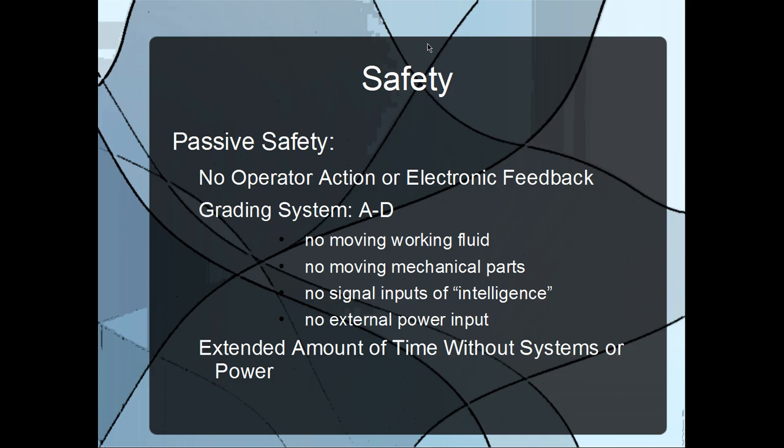By doing this, many old-style active safety systems are either no longer required, such as loop-installed and pump-driven emergency cooling systems, or are only installed to meet legal requirements, such as borated solution injection systems. Now, combined, the passive systems of today's pressurized light water reactors provide a new level of safety never experienced in the nuclear field. The NuScale power module, for example, operates all of its passive safety systems without pumps, AC or DC power, or addition of water.